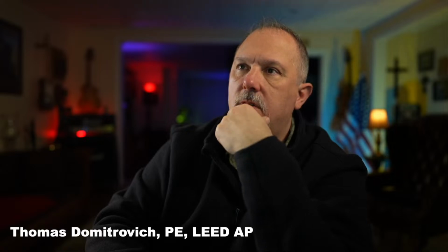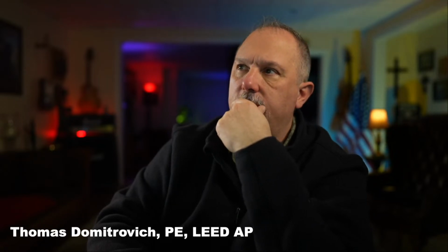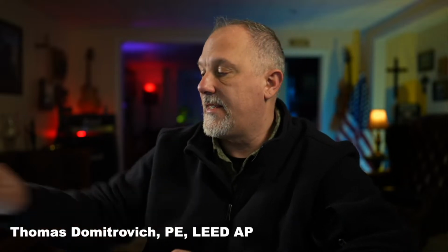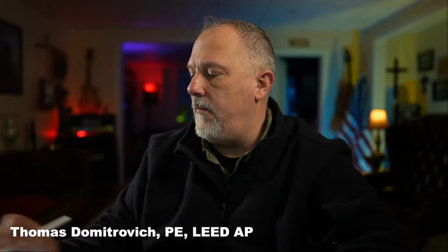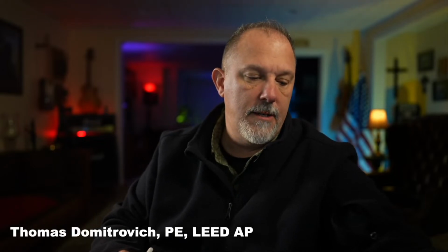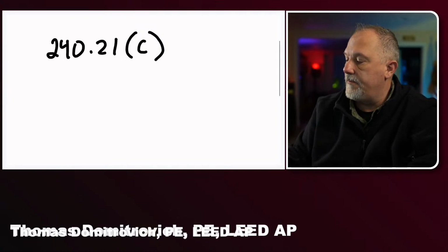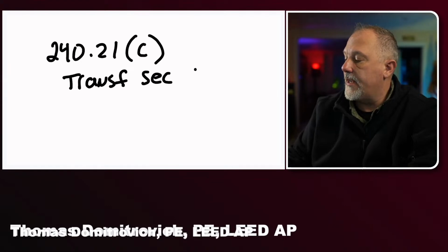No. Is it 240.21? 240.21, location in circuit. If you go to location in circuit for the overcurrent protection, there is a part C. My reference here would be 240.21, first level subdivision C, which is titled Transformer Secondary Conductors.